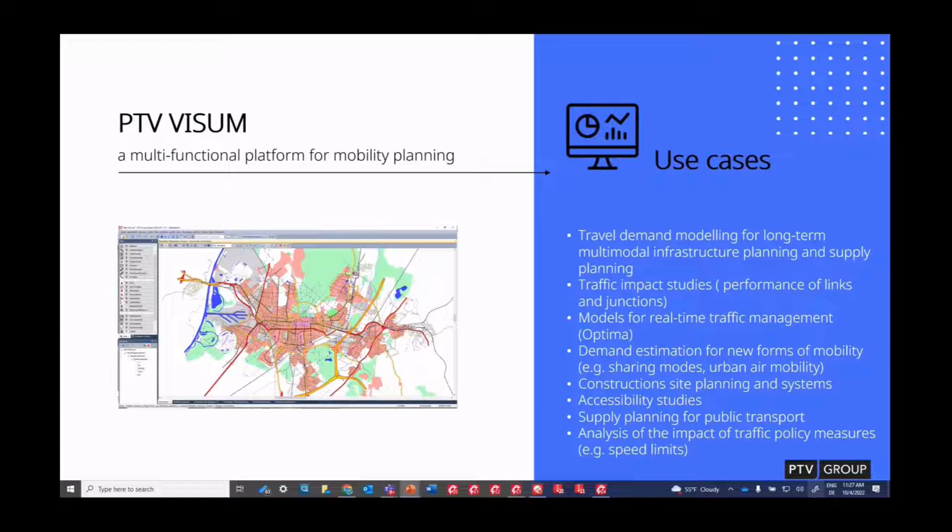Once you have a Model2Go model, you can do all the things that you could do with vZoom, with the travel demand model, basically. You can use it for travel demand modeling, for long-term planning. You could use it for traffic impact studies. Now, what we have so far with Model2Go isn't going to give you everything you need for a traffic impact study. There's not much signal timing in there, for example, so you're going to have to add that to it. But you're going to start with a model that's got good geometry, good data, true shape networks, has a zone system, has connectors, things like that. So it's really a seed or a foundation for a lot of this stuff.